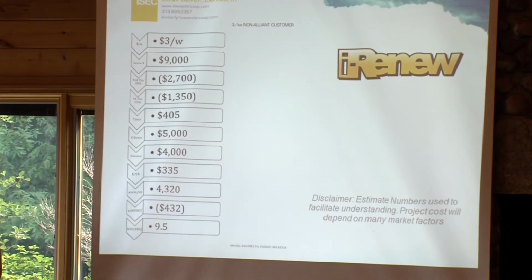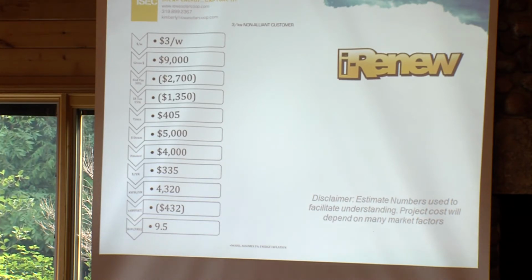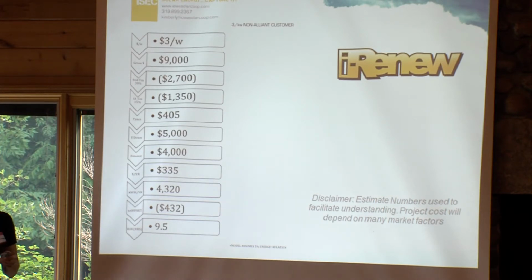Now what did I say with the Alliant Energy rebate? It was 5 years. So it adds about 4 years across the board, whether I run the same scenario for a 5 kilowatt system or a 30 kilowatt system. Without the Alliant kicker, without the utility rebate kicker back, it adds about 4 or 5 years to your investment.